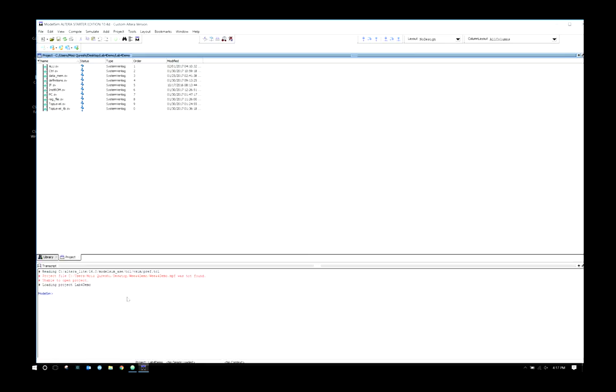So just like Quartus, you have an output of what ModelSim is going to give you to see. You also have to compile in ModelSim. So I'm going to show you the flow of what you have to do to test and run everything again if you make a change. The first thing you want to do, we have all these question marks. That's saying in ModelSim that this stuff needs to be compiled. So I'm going to hit compile.